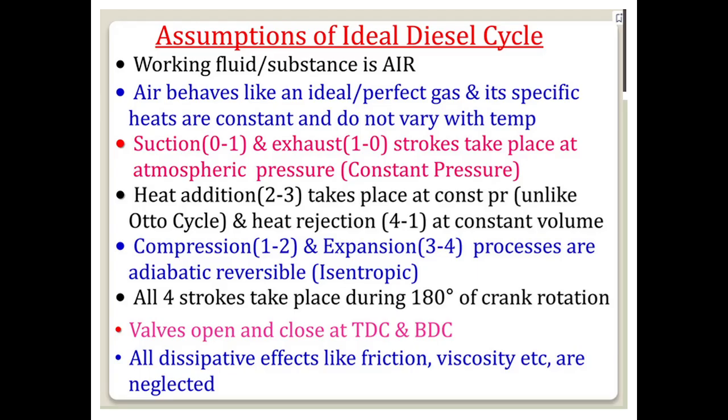Now these are the assumptions and these all are the theoretical condition, ideal conditions. Heat addition takes place at 2 to 3, heat rejection at 4 to 1, but ideally it is not possible. Even the valve open and close exactly at TDC and BDC respectively. All the four strokes take place during 180-degree crank rotation. All the effects like friction, viscosity are neglected in the ideal diesel cycle.